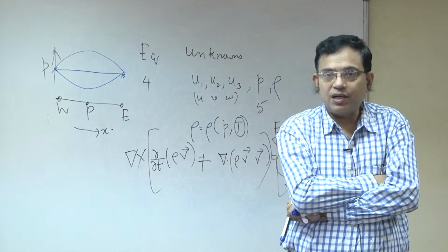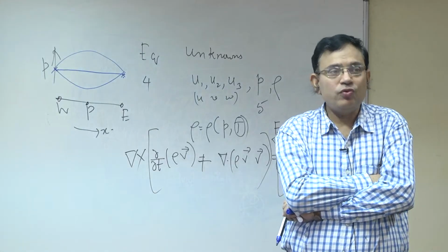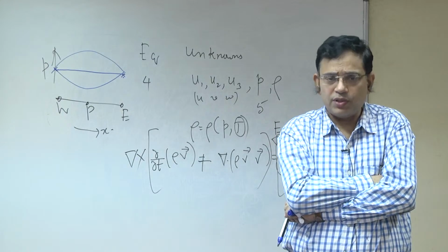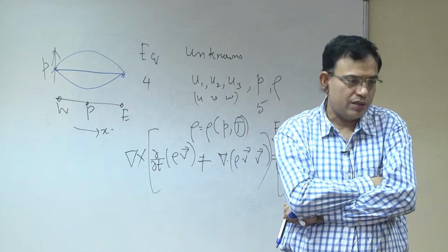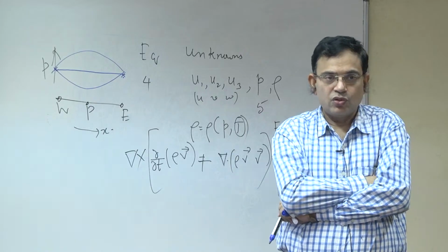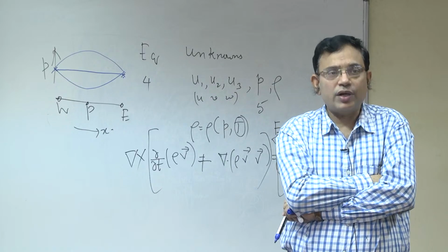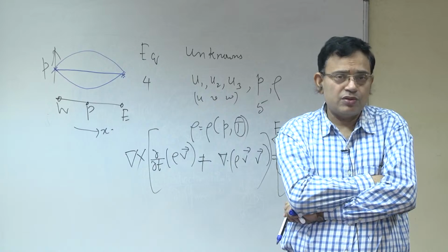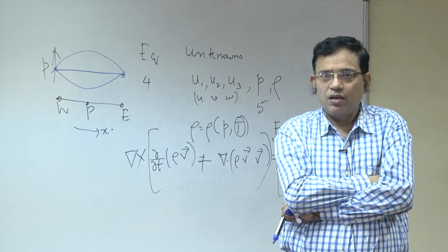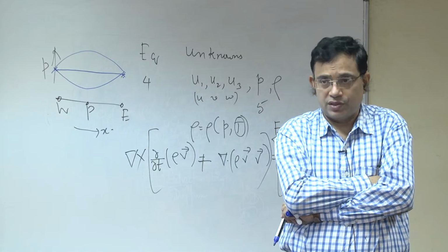The staggered grid had a problem when we are trying to do linear interpolation, but if we are using higher order interpolation functions, then actually it is not necessary, because then it can accommodate the effect of P. So, collocated grid formulation also is quite common, and when these subjects developed, they all developed with the geometry of these rectangular type of grids.